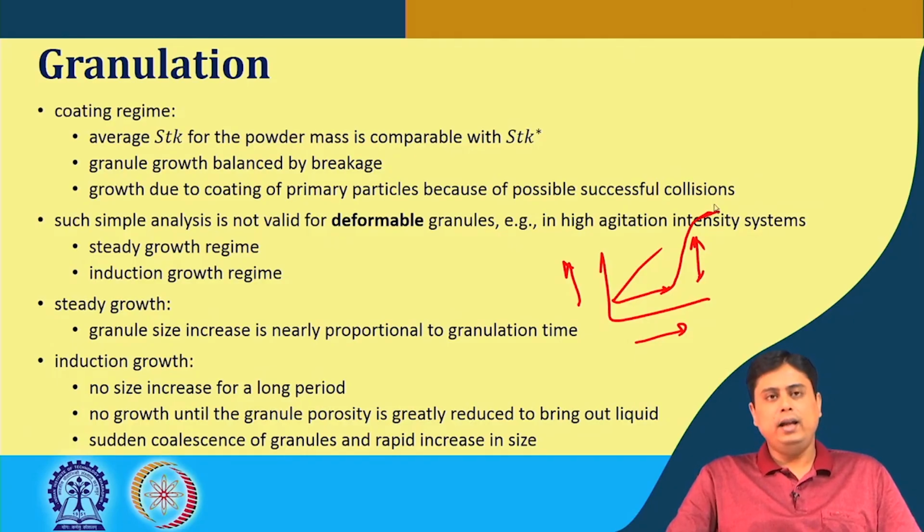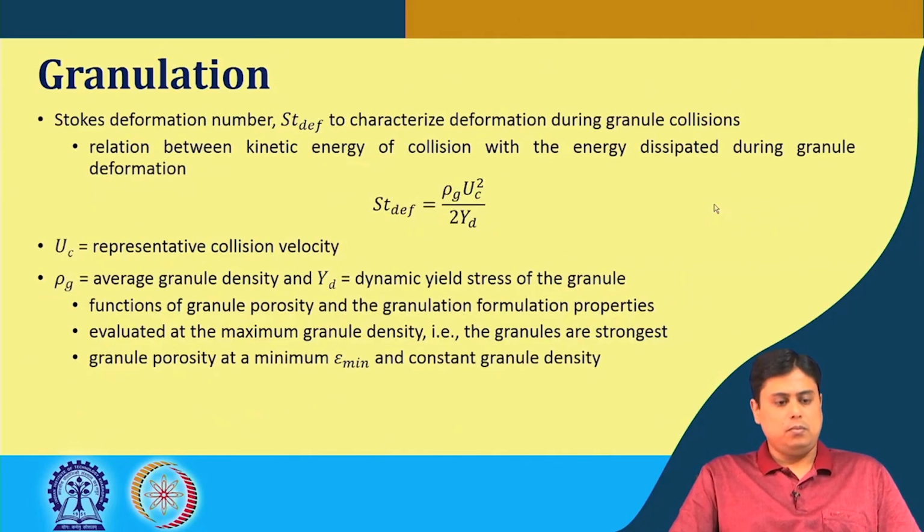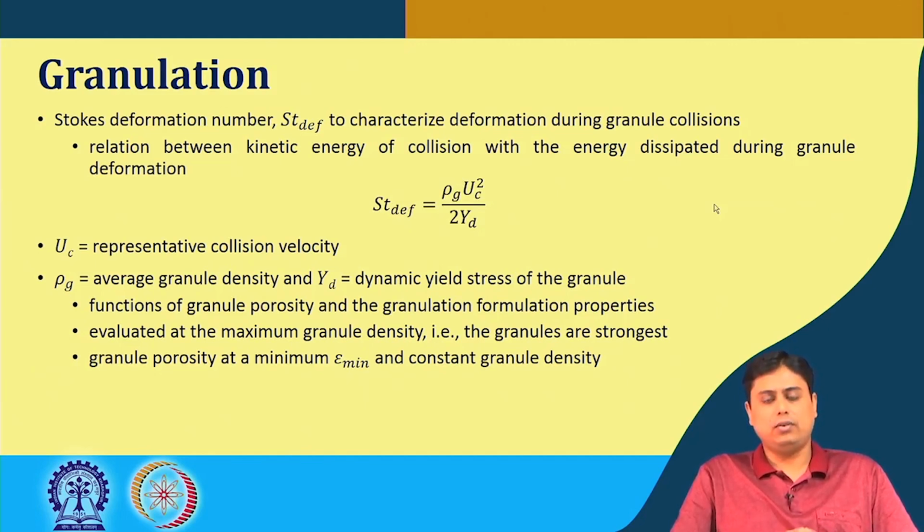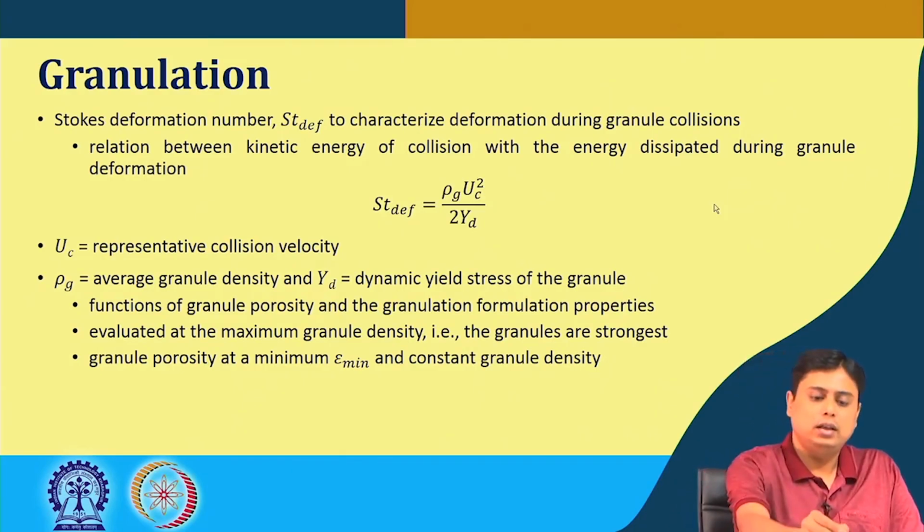So, this is the induction growth regime in the case of deformable granules. Now, in order to characterize the deformation during this granulation, the Stokes deformation number has been defined, which relates the kinetic energy of collision to the energy dissipated during granule deformation. The Stokes deformation number is defined in this manner.